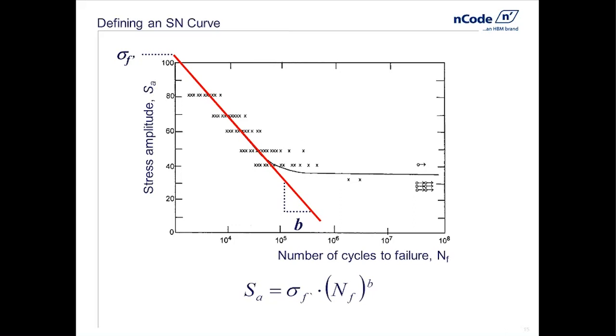In this case, following Basquin's approach of plotting the log of stress and the log of life, we can regress that, curve fit that with a linear regression, and we find out then there's usually a pretty good relationship. Now this is not the only way to fit an SN curve, but most typically a linear curve is fitted to the log of stress versus the log of life. Think about your math here for just a minute. What's linear in log-log space? An exponential relationship, power law relationship.